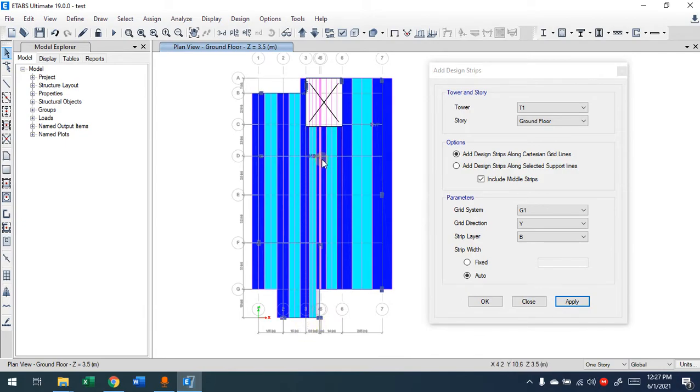Oh, this is the problem we have in asymmetrical buildings, that you cannot simply say, okay, this is the column strip, this is the middle strip. For symmetrical buildings, yes, even in reinforced concrete design, the column strip and middle strip can be used if you have, for example, a minimum amount of slab beside each other, and the difference between their dimensions is within this ratio. Then you can use this middle strip, column strip. I have to show it to you, and you need to know how to do these things.